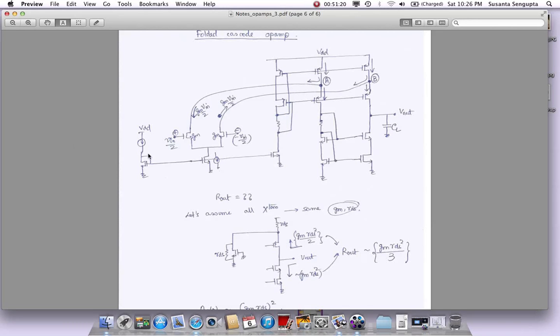So you got some sort of biasing circuitry here, some current mirrors to provide the tail current. The input stage gives some current, but there is no voltage created here till it goes to the output. So all the flow here is happening in terms of currents, and when we do currents, then there are many low impedance nodes you would see here as the current flows, as we'll trace it.